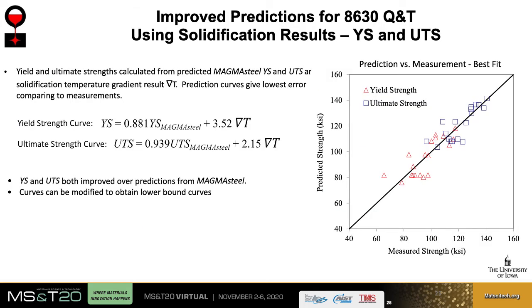Using the modeling results, modeling parameters were correlated to measured tensile properties to establish prediction curves that move us towards the capability to predict the lower bound properties. Currently, casting simulation software can predict strength properties, but it is not accurate. In this preliminary analysis of this specific dataset, thermal gradient seems to correct the over-prediction of the software. Further analysis is needed to establish this relationship and to identify what other parameters can more accurately predict properties.